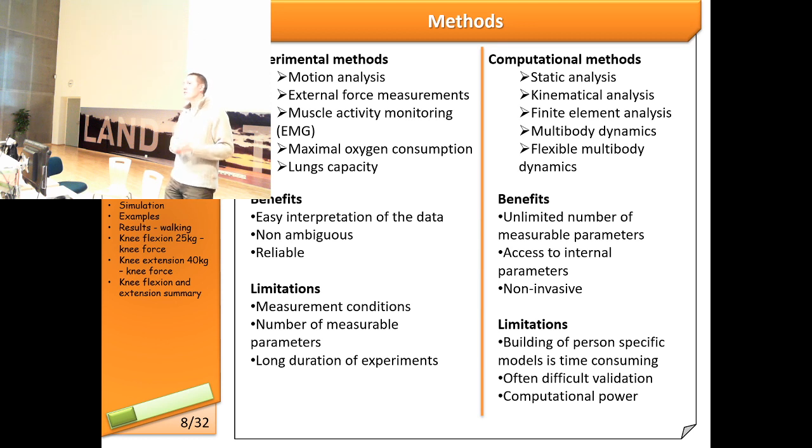We can measure external forces. So if you're walking, you can have a force plate on the floor, and while you're walking you can actually detect the force. You can have only the vertical component, but let's say see the distribution of the force under your soles. Or you can have a system that will measure the force in 3 directions plus the torques, and it will give you the location where the center of the force is applied under each leg, but will not give you the distribution of the force. So these are the options that are currently available.